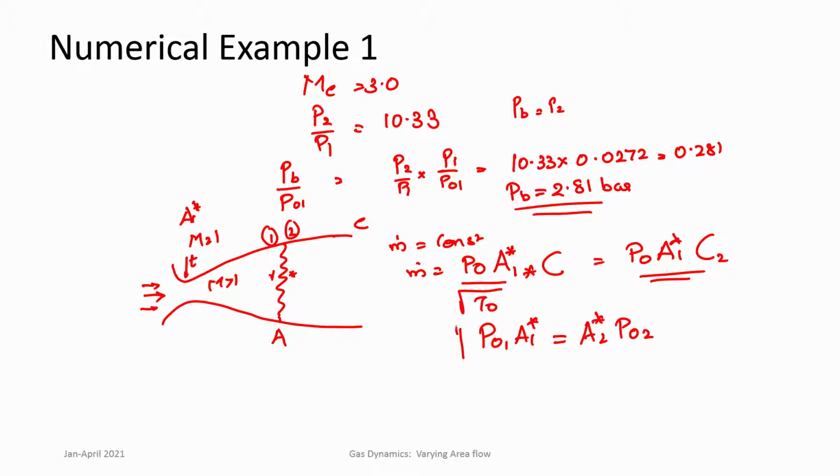So this is the guiding principle which will allow us to solve such problems. There is an entropy generation at the shock. As a consequence, the stagnation pressure changes. This principle, if you remember, applies in many cases in variable area ducts, which we will discuss more often in diffusers, where shocks can be easily seen. The way to solve such problems is to use this guiding principle. So how do we go with this problem?